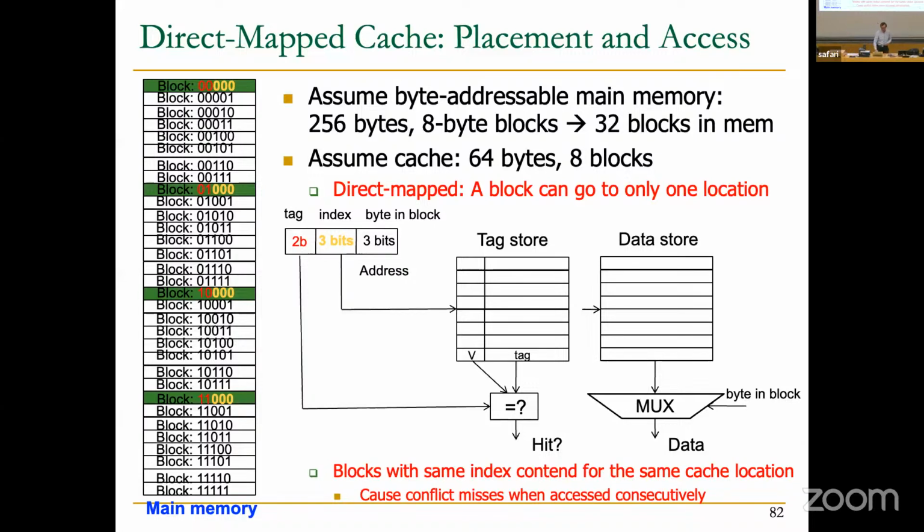You know how to build this. This is the memory structure. Remember, we had a memory structure that had 4 locations and 3 bits each. Well, now we have 8 locations, and in the data store we have 8 bytes each. Okay, in the tag store, now you can calculate. We have actually 8 locations with 3 bits each. Not too bad. So that picture that we actually constructed, you just need to double it, let's say, right? So tag store is much smaller than data store.